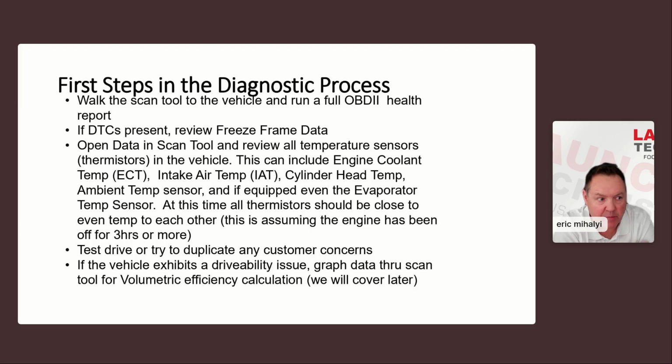Well, if the car was going 47 miles an hour in 4th gear with 41% engine load, and you're trying to recreate the problem with it idling in the bay, you might not be successful in recreating the customer's problem. So freeze frame data is extremely important in setting the parameters. When I do test drive this car, I'm going to try and recreate what was happening to see if I can get the failure to happen a second time.